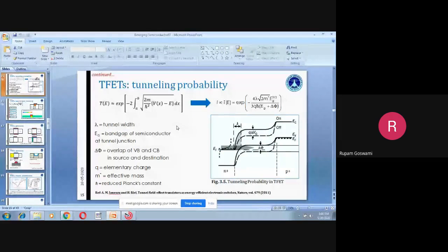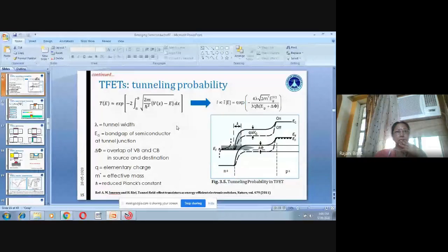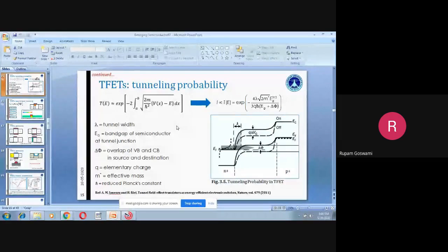And secondly, Ms. Chauhan, there is another question. Can't SiO2 be etched entirely from the cavity? Probably this is with relation to biosensors. If it is necessary, then what is its thickness? Actually, you cannot, as there is a very great risk of damaging the surface of your semiconductor if you try to etch out the entire silicon dioxide.